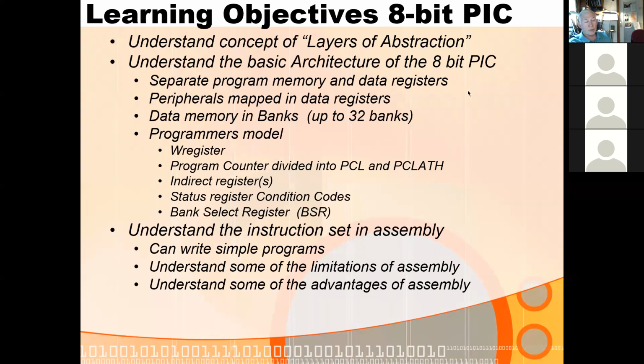On the data register side, you have 12 bits of address in the address bus, and you have 8 bits in the data bus. So the data bus is much smaller, almost half the size, and the address bus is also 3 bits smaller. So it's only 12 instead of 15. So on the program memory side, you can have up to 32K. On the data memory side, you can only have up to 4K.